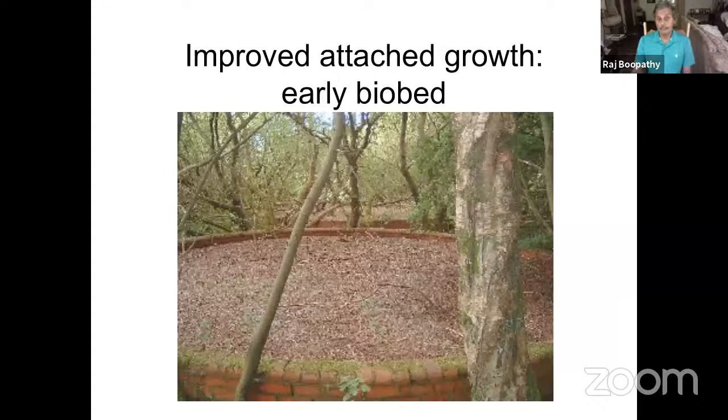And then we have an early bio bed. You can put wastewater going through biological materials, and we call it a bio bed. And then again, the same principle: bacteria is growing on this biofilm, and the wastewater is pumped through, the same concept. So you retain the biomass inside the reactor for a longer period of time.